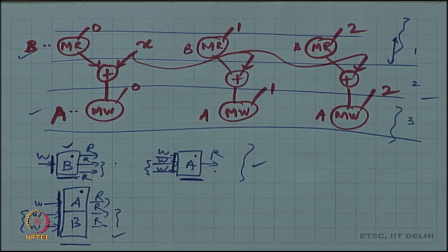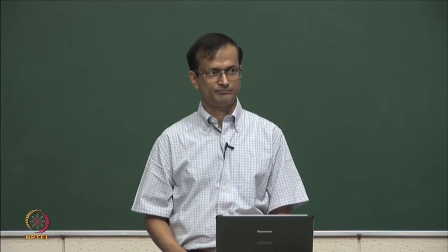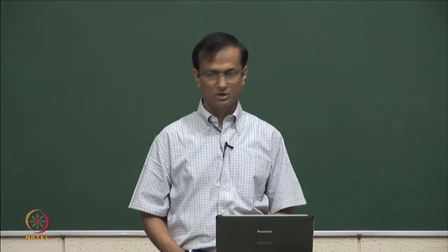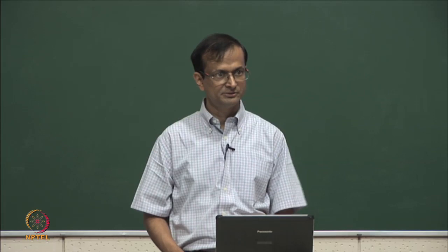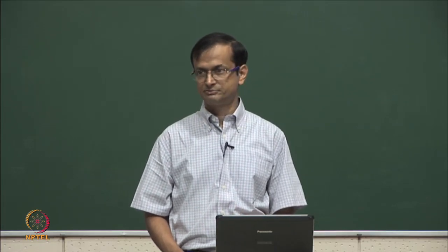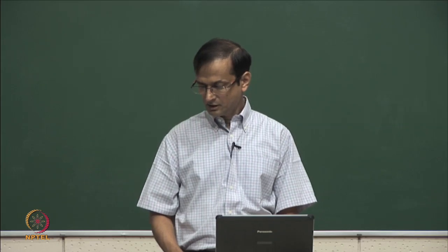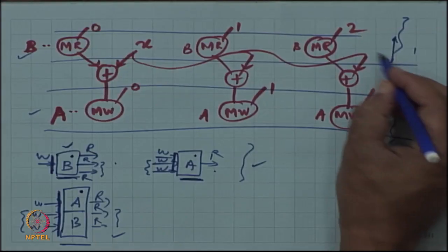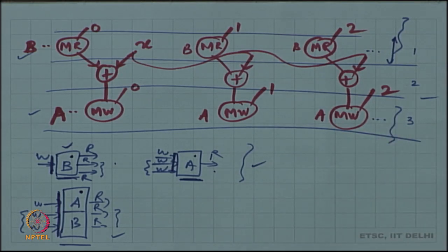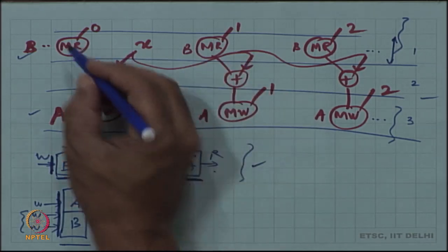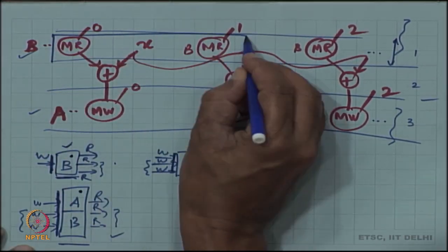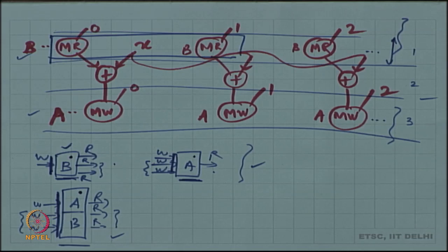But the way to formulate the problem then could be that you are provided memory resources. Let us say these are dual port memories or 4-port memories or something. It is fixed, memory properties are fixed. Then how would you argue? Essentially, all of these 100 operations do not proceed in parallel. If I give you only a 2-port memory, then 2 out of the 100 independent read operations that are there, you can schedule in parallel.